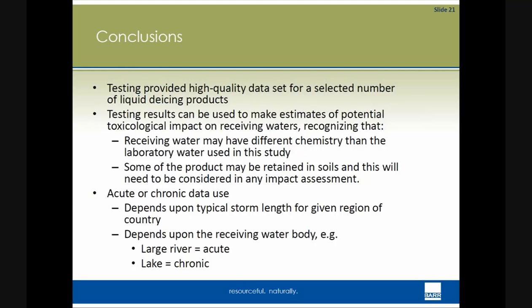So, for example, if you want to figure out what amounts of deicing product will not cause any toxicity at all, you could use that NOAEC value for a particular chemical. Use it for adapting UV, for example, and calculate how much runoff can go off that road deck into that pipe, into that stream, and not cause toxicity.